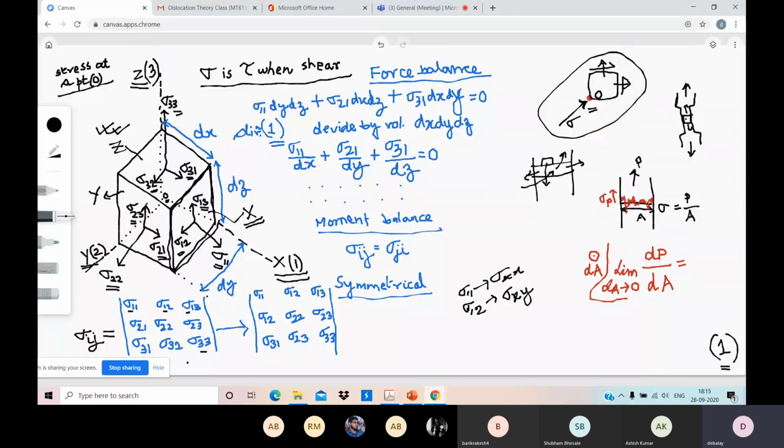So this is called the stress tensor, that whatever way you load a body or apply stress, in whatever angle, whatever magnitude to a point in the body, it can be resolved into 9 components if you consider a box around it. And stress at a point can be represented by assuming that the box that you are considering is very small.